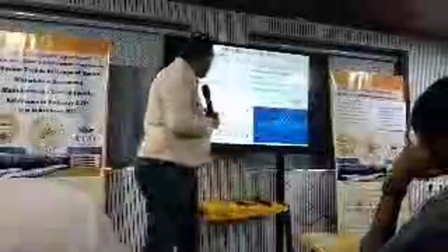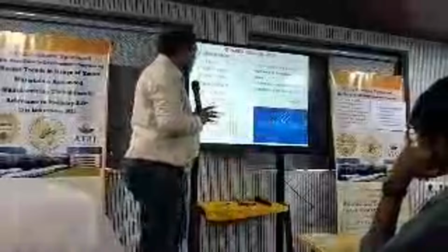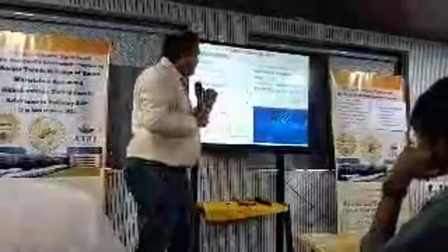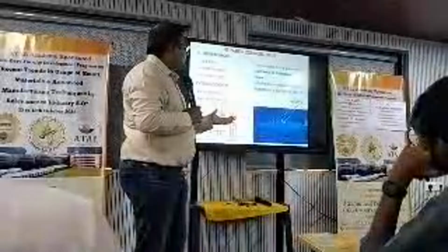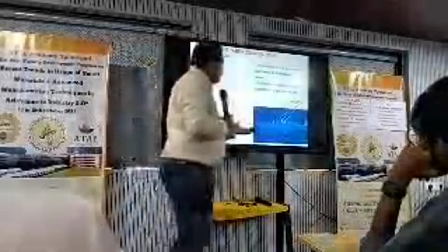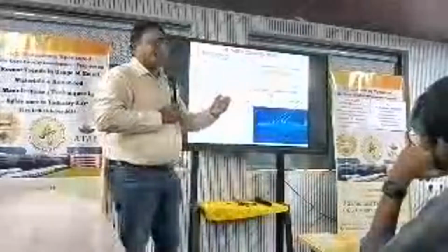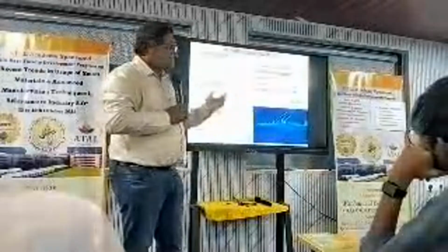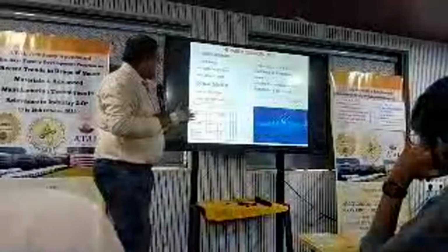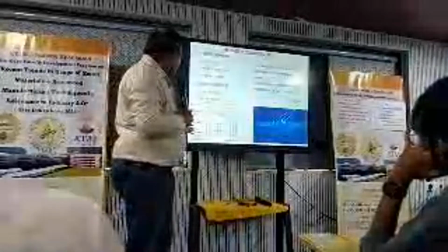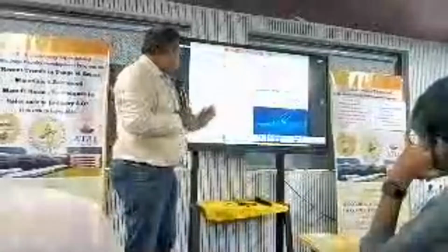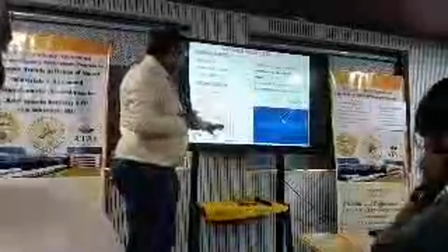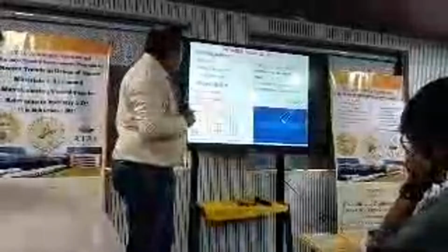So we have to find out the path from the source to receiver, and we have to reduce the temperature of the path. Before that we have to do the analysis, and we have to find out the complete temperature and how to reduce the hot spot of the temperature. If you see the hull temperature around 30 degrees, plume temperature, plume is the exhaust gas center point, around 380 degrees, exhaust duct temperature is 380 degrees. So all these temperatures, if you arrest, we can reduce the temperature.